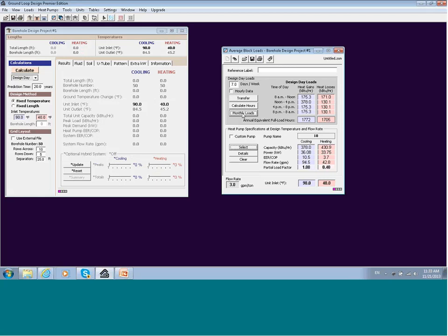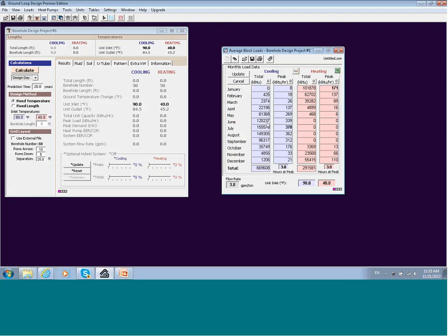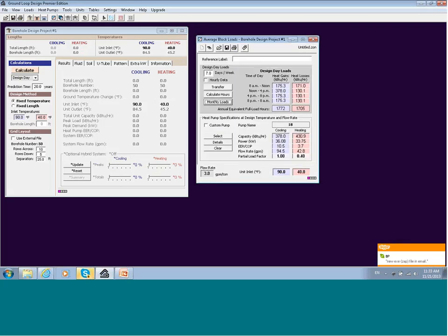However, with monthly loads, there's simply not enough data available in these load profiles for the program to know exactly when things are going to be shunted on the peak and the monthly levels or total levels. So as a designer, you have to have some control to do it manually and make your best estimate, essentially. So for example, let's do a preliminary design assuming 100% geo here.